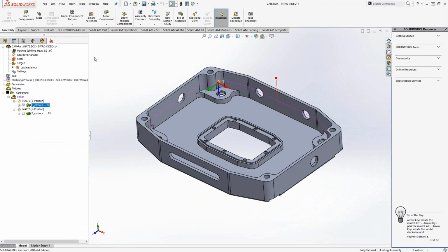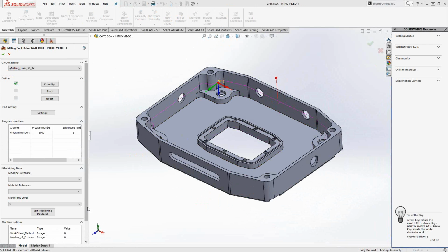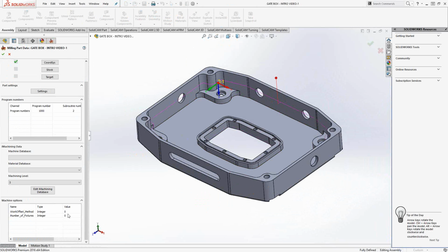I could actually use maybe the transform commands like you've seen in previous videos, where I transform it, translate, or rotate, or whatever I need to do, or I can do it simply by going to double click on CAM part, iNumber of fixtures, and if I want to post out to all 4 of those offsets, I'll put a number 4 in here. So that number actually translates to the number of offsets I'd like to post it to.